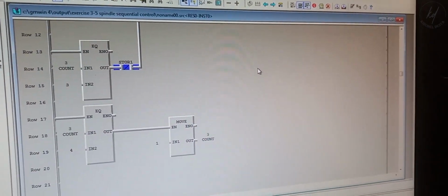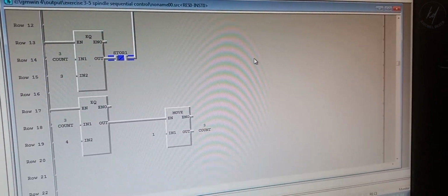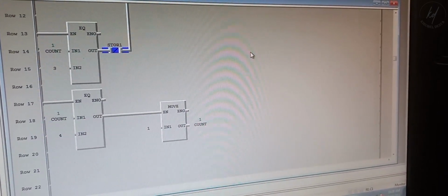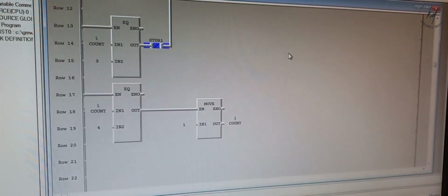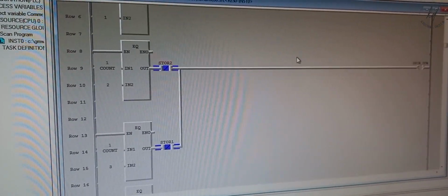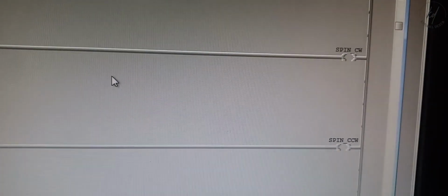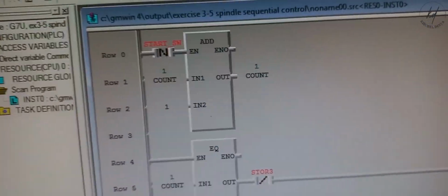As we see from the ladder diagram, 4 equal-to comparators are found, 3 of whose outputs are connected in series with each of those position sensors, and the remaining 1 is connected in series with the move command. The only difference between those 4 equal comparators with regard to parameters is their in2 pin, that is the second input value, which makes each of them unique.